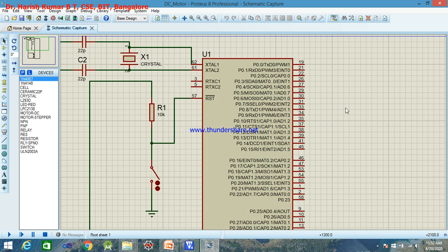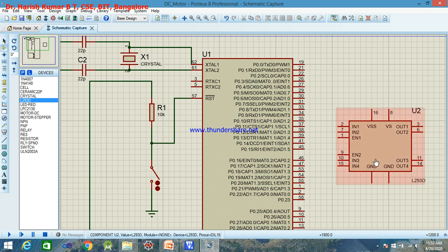Now if you want, you can take a DC motor and connect it directly to P0.8 and P0.11, but it will not run that accurately and precisely. Now every external device will have its own controller, or sorry, instead of controller I have to say drivers. Now I'll use the driver here, this one. Now L293D, okay, I'll use it. Now through this I'll connect the DC motor.